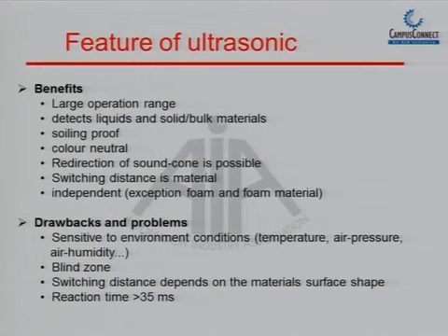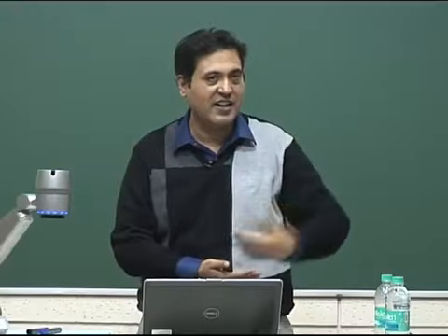Then basic application, if we talk about ultrasonic sensor, is for level measurement. You have a water level tank, you want to measure the level of the tank, you mount an ultrasonic sensor on top of it. As the level goes down, you can get a switch output for that, and you can start refilling the tank all over again.